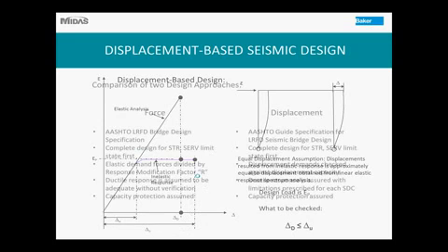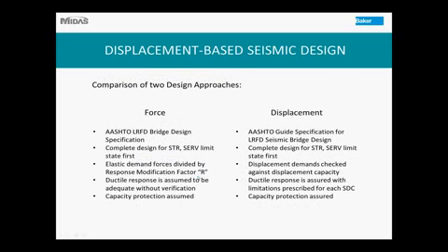So, comparison of the two design approaches. The traditional force-based design is accommodated by the AASHTO LRFD Bridge Design Specifications right now, and the displacement-based design is accommodated by the AASHTO Guide Specifications for LRFD Seismic Bridge Design. Both methods require you to finish the strength and service limit state checks first, and then go ahead with your seismic design.